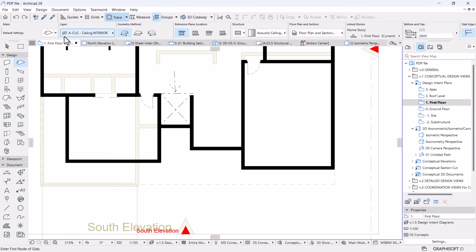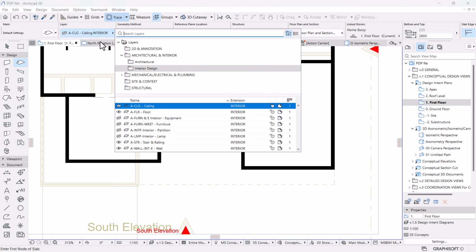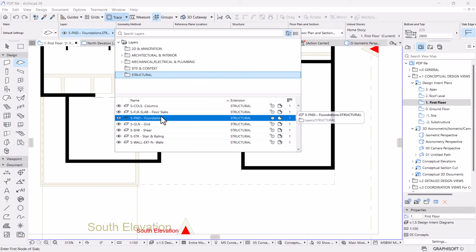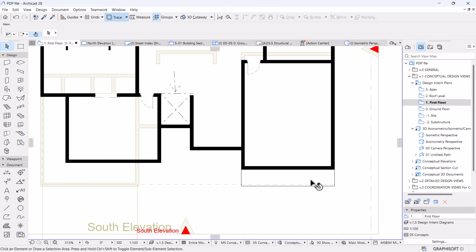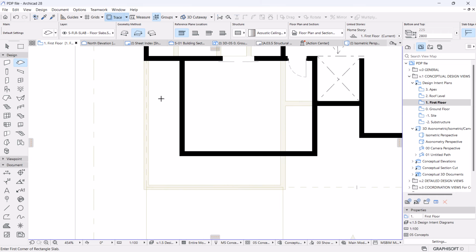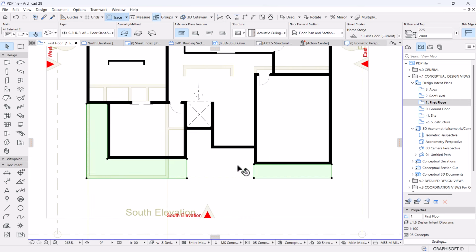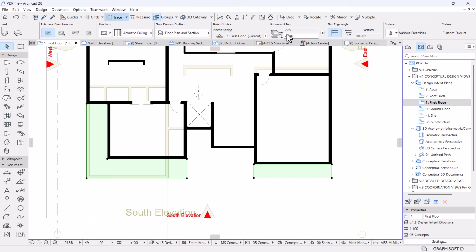I can just quickly add a slab, and this slab should be under structural slabs, right? So I'm going to place the slab like that here of 6385 by 1.2. Okay, this basically will be our balcony, and then to the master wing also we need to place this slab for the balcony, and then it's going to be all the way like that. And so normally you would have a step down of this, so I'm going to, instead of 2.8.